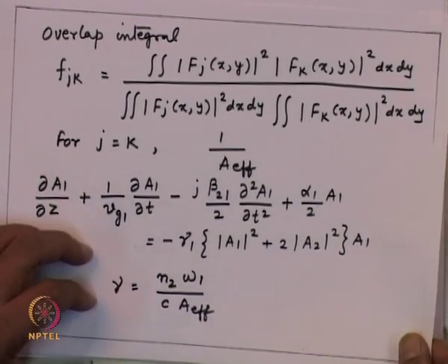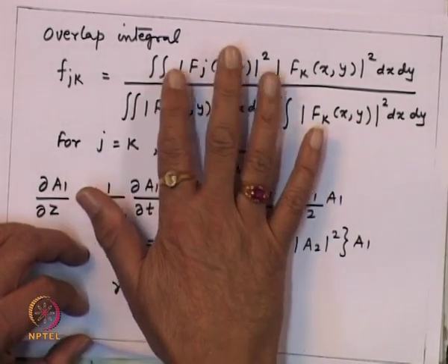When you are having a multi-channel transmission, the same third order susceptibility gives you this phenomena of crosstalk due to nonlinear effects. The same phenomena, when I look at it, gives you one more effect, and that is what is called the four-wave mixing phenomena. Now, what is the four-wave mixing phenomena? This phenomena, if I compare with an electronic system, is identical to what we used to say as the interchannel mixing or intermodulation products.